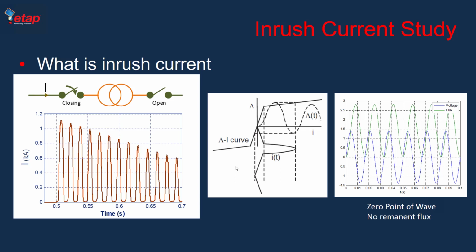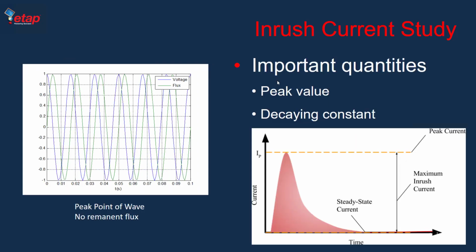Now, when it comes to system design, the system needs to be able to tolerate that amount of current drawn, basically the harmonic content, and the protection system needs to restrain during this current. This is way above the normal loading conditions. So typically this type of analysis is done in electromagnetic transient analysis, EMT-type software.